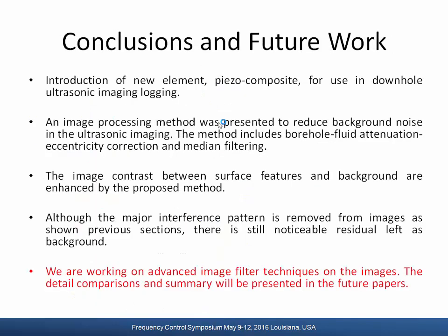Okay, so I would like to move on to the last section, conclusions and future work. I briefly talked about the piezo composite transducer, including the excitation functions, the frequency spectrum and beam field. After that, I moved on to the processing method, which includes the borehole fluid attenuation eccentricity correction and median filter. Based on the field example, we can see the image contrast between the surface features and background is significantly improved.